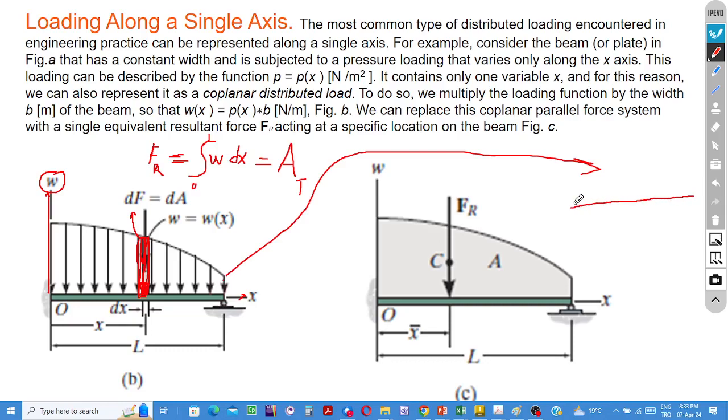At point O, we have the resultant force of the distributed system, and it is applied at point O. If we apply such a resultant force at point O, considering the rotation effect of the given force system with respect to point O, then the given system and that new system will be equivalent.